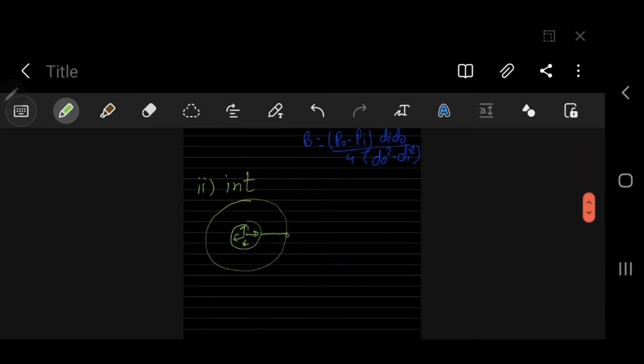The magnitude of radial stress at the outermost point, that is this point, will be zero, and as we move from outside to inside along the radial direction, the magnitude of stress will increase. Okay, so this will be the radial stress.